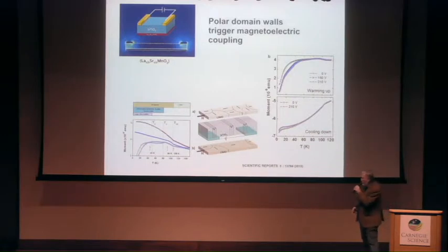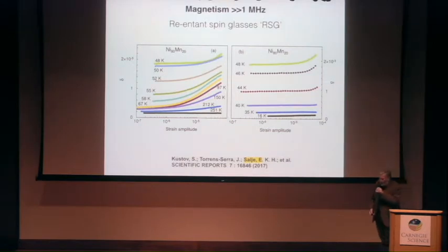Another one is with Franco Biata in Barcelona. We looked into magnetic coupling, so we take the STO. STOs are ferroelastic material. We put a magnetic layer on there, and then we cool it down, and we see what the domain structure in STO does. We have the magnetic layer on top of it, and what you find in all these data is that the pinning of the magnetic domain walls at the interface between the STO and the magnetic layer is actually non-zero. It's not extremely strong, but it's quite strong, and so we can change the magnetic properties by the underlying STO.